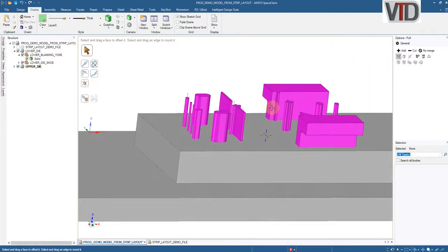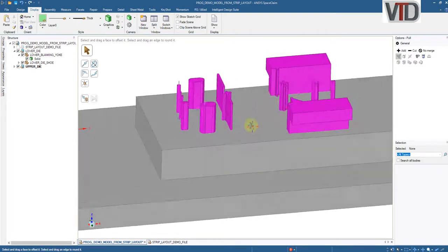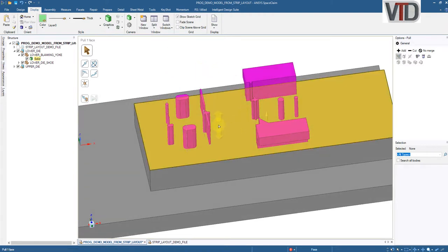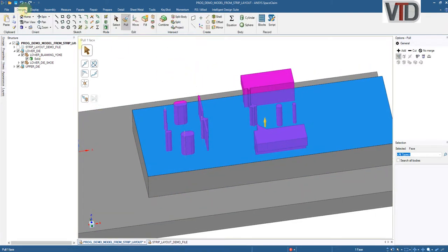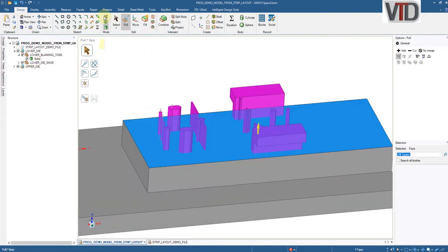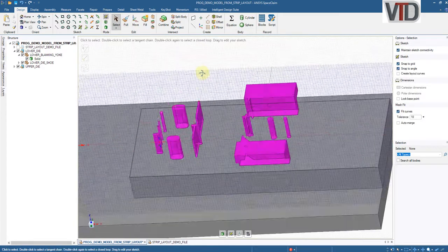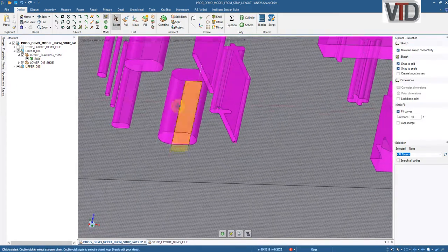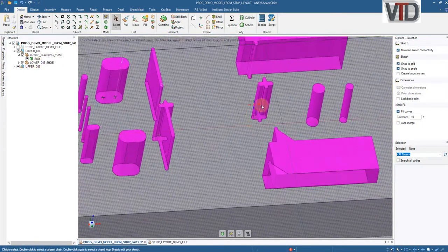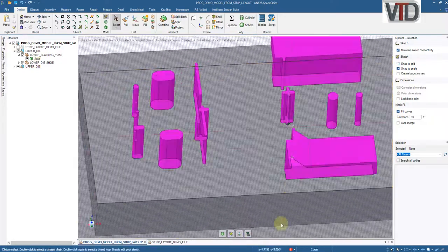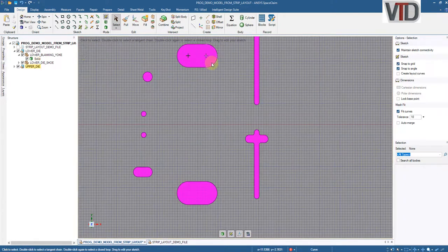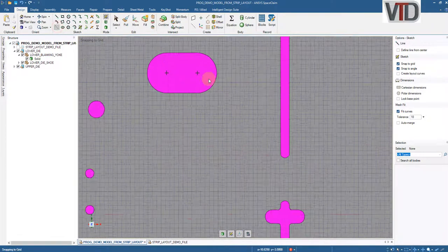And so now you can see I've got trim sections that are entering into the lower yoke. Now, one of the nice things about this software is every time you go to do a sketch, it basically looks like you're creating a cross section. So now that I've got these interfering with this, I can turn on the sketch and you actually can see an outline, and that's usable geometry. If I want to be able to use it, I can actually use that geometry. So it just makes it a lot easier for you to see kind of what you're trying to do sometimes. And it also gives you working geometry that you can work to if you need to.